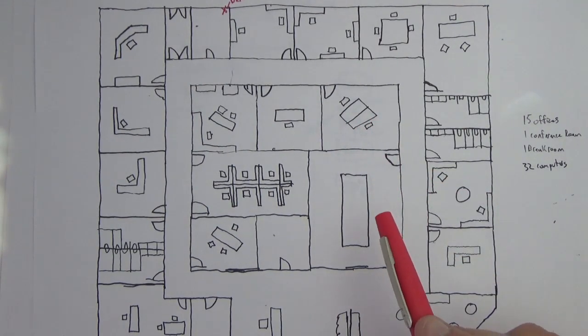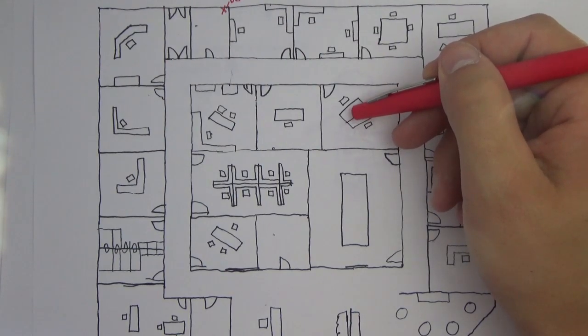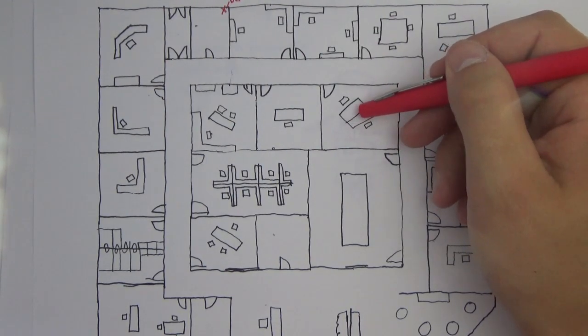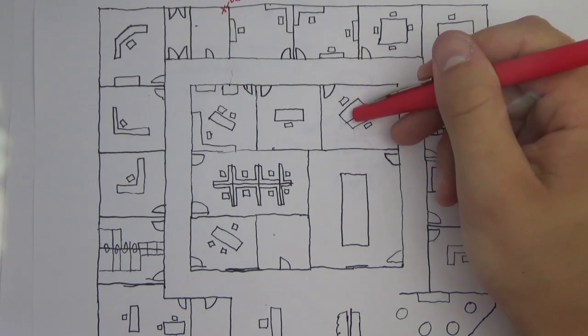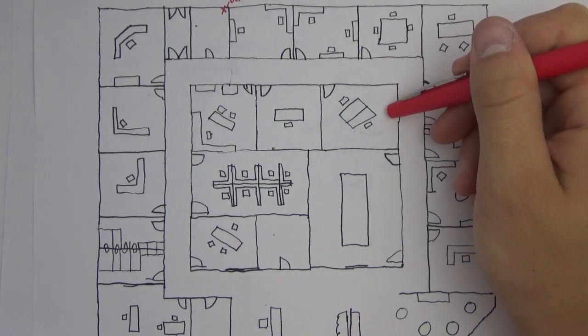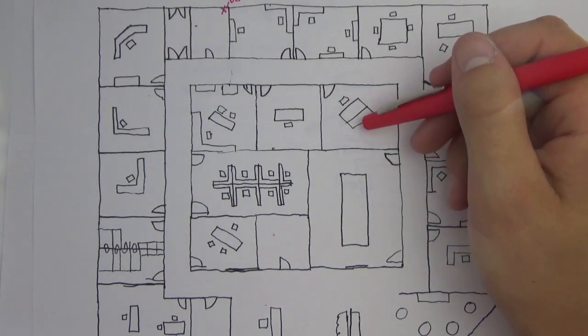If I'm coming up from below, I might actually be able to put a floor plate right in the middle of the room underneath these two desks. The problem is, what if these two people realize that they don't really like facing each other day in and day out, and they decide to move their desks up against the walls? Well, now their network connectivity is going to stream from the middle of the room off to a desk. And guess what's going to happen? Well, people are going to be walking right through the middle of the room. They're going to break something.